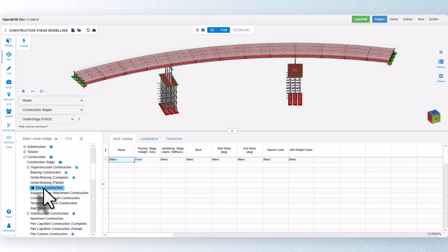Concrete is poured into the formwork and leveled to create a flat surface for the deck. Fifth, finishing the surface. The surface of the concrete is finished with a trowel to create a smooth, even surface. Sixth, curing the concrete. The concrete is left to cure, typically for several days, to gain strength and durability. Finally, applying the wearing surface. A final layer of asphalt or other wearing surface is applied to protect the concrete deck and provide a skid-resistant surface for vehicles.